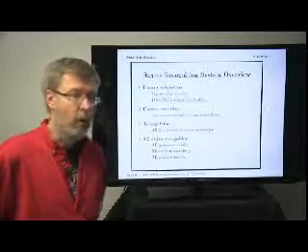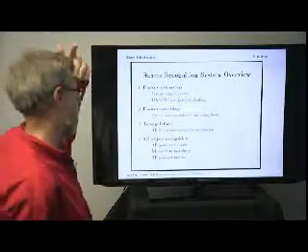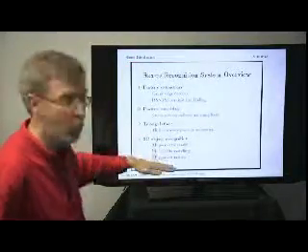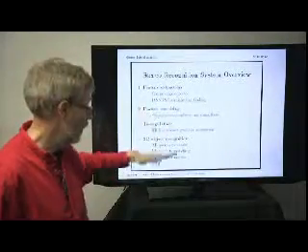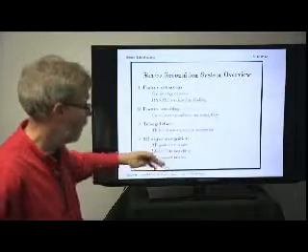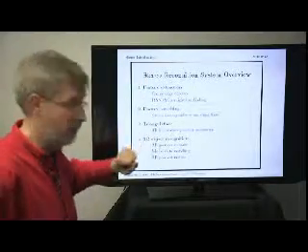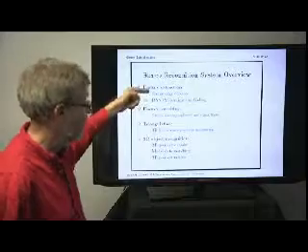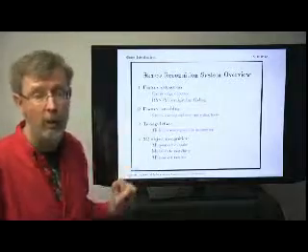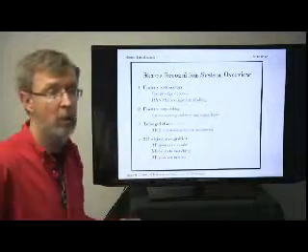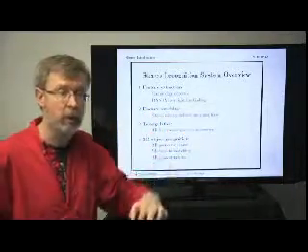All right, what we're going to look at over the course of these lectures is summarized here. We want to go all the way from the raw images at this end, down to a recognized object, in this case these little wedges, at the very bottom of the system. We're going to go through a variety of steps when building the stereo vision system. We'll look at the Canny edge detector, which is a way of finding little edge fragments. We'll take those edge fragments and turn them into longer straight line sections. Then we'll do feature matching between the straight lines to get our correspondences between the left and right image.